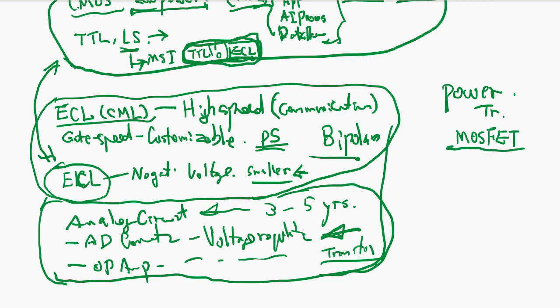The reason is bipolar was initially used for power transistor, but bipolar is current driven, and MOSFET, as you know, the gate draws no current, and when you handle a high power like 20 amps, you don't want to drive this with a 1 amp gate. The gate current is almost zero current. You can still turn on and off.